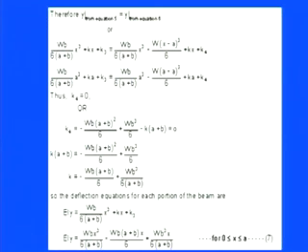So now by equating both of these deflection terms which we obtained in the previous section, WB by 6 (A plus B) into x cube plus kx plus k3 equals WB divided by 6 into (A plus B) into x cube minus W (x minus A) whole cube divided by 6 plus kx plus k4. So this deflection term is there for the AB portion, and this deflection term is there for the BC portion.